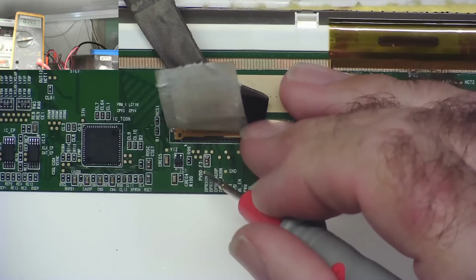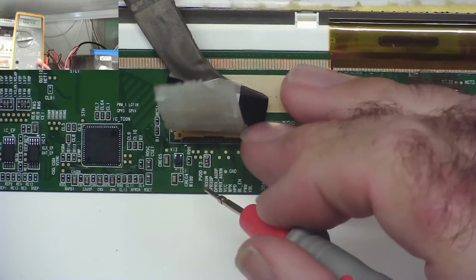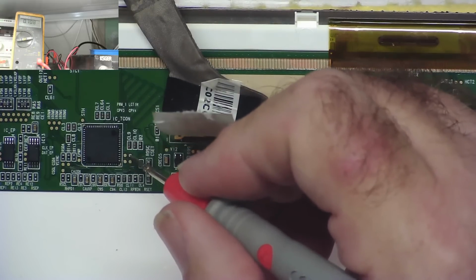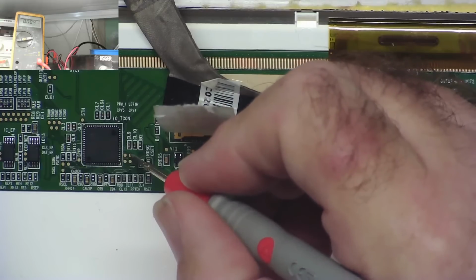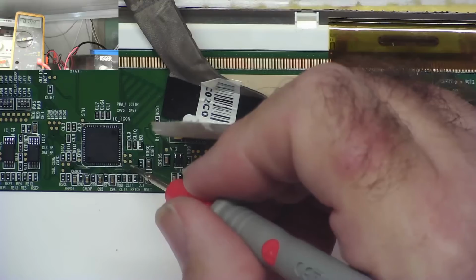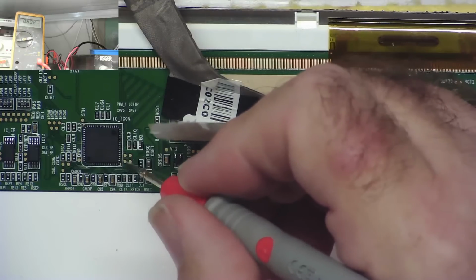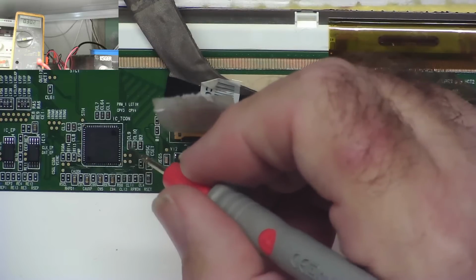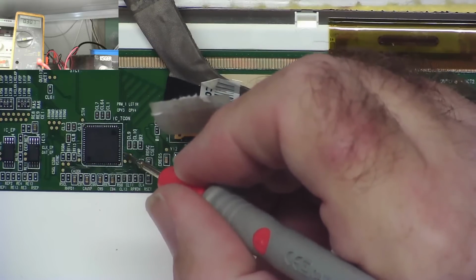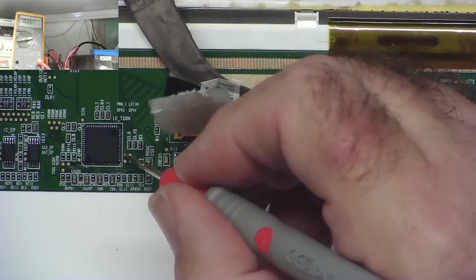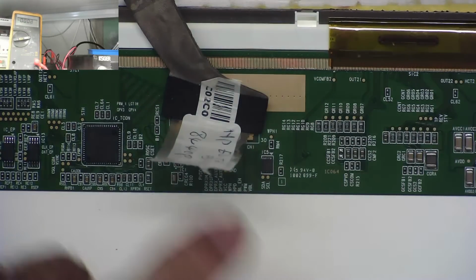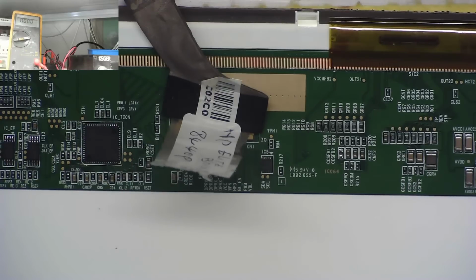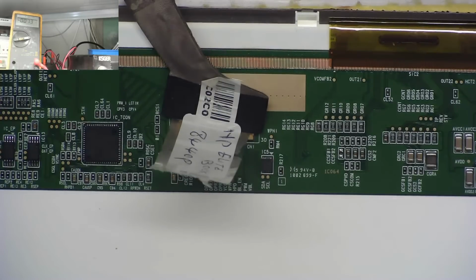PVDD down here is 3.14. Call that good enough. And then down by this T-con we had 0, 0.919. Close. 0.919 again. 0. Oh no, sorry, it was 0.31 on the other one. 0.307. Yeah, so those all look the same. I think what we need to do is continue around this board and have a look at the other test points we can see, and see if we can actually spot something that is not the same.